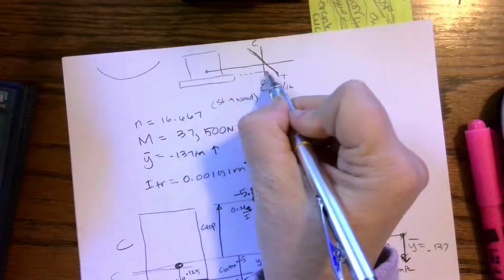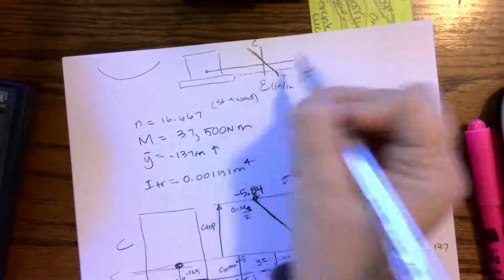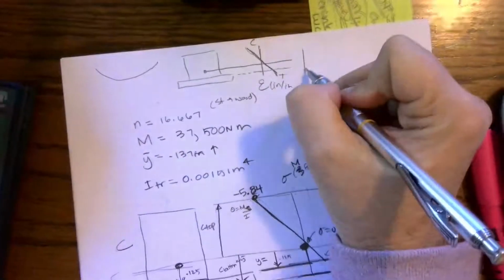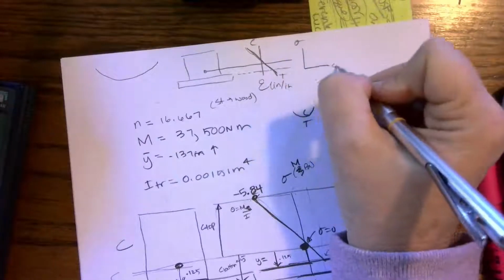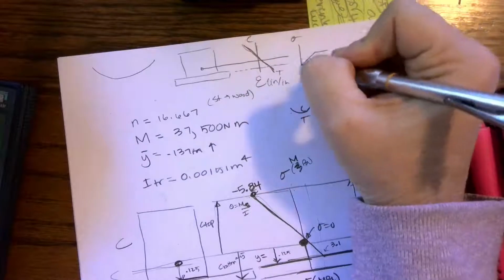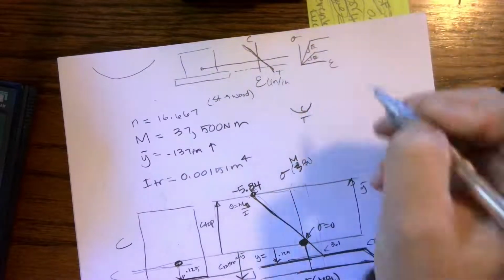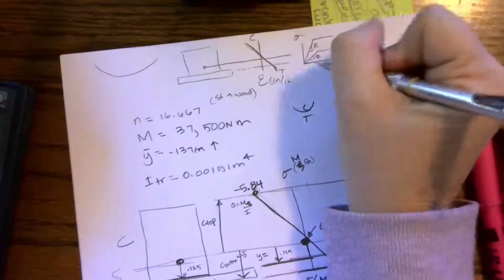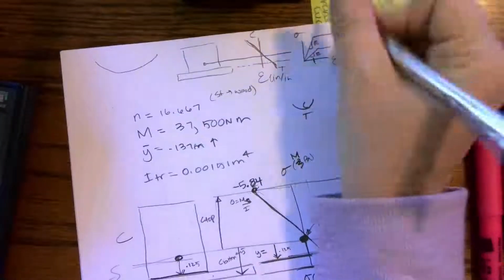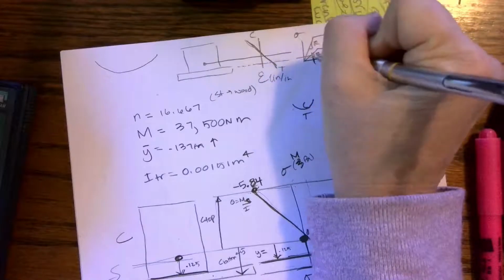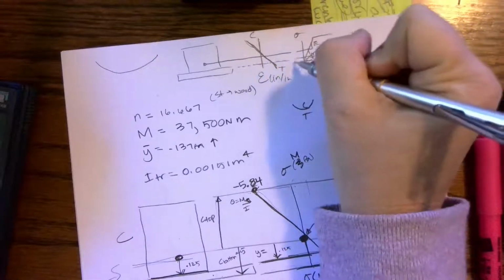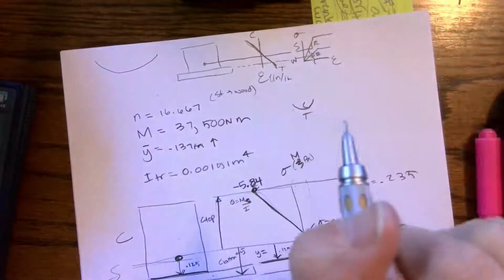But because right here I have two different materials at this same piece, remember that when we have a stress strain curve, both of these are going to have unique values of E. Our modulus of elasticity is different. So I have one strain, and then I'm going to go back and see, okay, I actually have two stresses. Here's my wood and here's my steel.